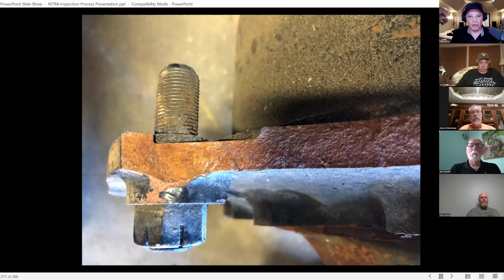I don't want to lose our flow here, but if anybody has any questions, I can send you a picture of it. It's pretty easy to identify. It's a flat plate and you'll see the bolts that attach to it. Very often they will pick up the brake boss, the threads that the brake drums attach to on the Clark hub, and then they'll pick up the wheel studs also. It's just like a girdle. Very often they'll integrate the rotor for the wheel restraint system right into that. So it's a really good way to keep those Clarks running without having failures or without having to buy the $2,000 hubs.